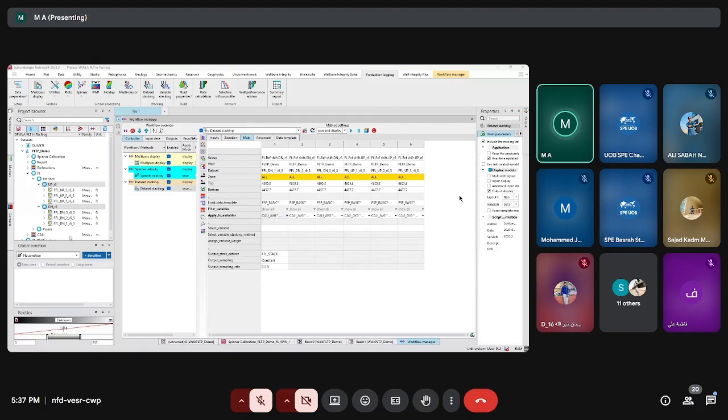As per this equation, you need the velocity and you need the area. So the area, that means you need what? You need the caliper. The velocity, since we have here 2 phases, you need the velocity of the oil, the velocity of the gas, and the velocity of the water. So that means you need to also identify the holdups for each phase.